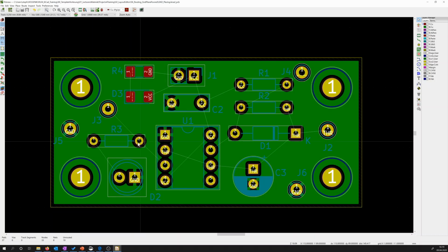If we look at our timing circuit on the right side of our PCB, the VCC is going to R1, and that's fine. R2, the test point for pin number 2 of R1, pin number 1 of R2, that's fine. Then threshold, pin number 2, parallel to the diode, we have the connections here, the connections here. Then we go to pin number 7, the discharge, that's fine, we have no crossing.